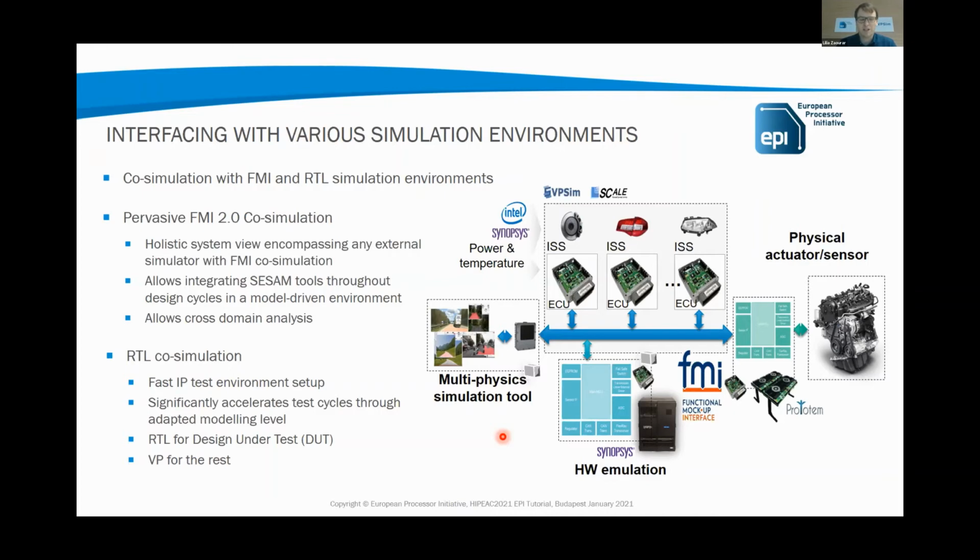And so this can be used, for instance, to co-simulate with sensors, sensor simulators, or simulators dedicated to other domains than the pure system virtual prototyping. We've used it, for instance, for simulating autonomous vehicles by getting the data coming from LiDAR, radar, and cameras and processing the data in a virtual prototyping of the ECU.